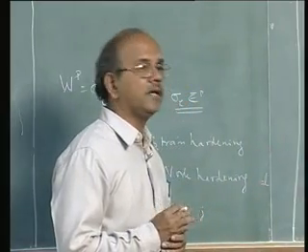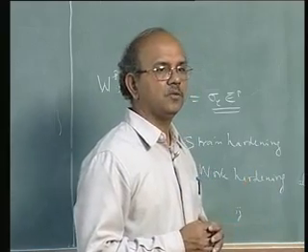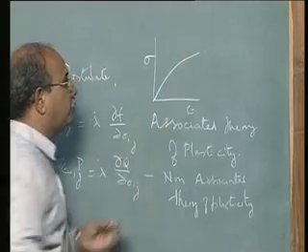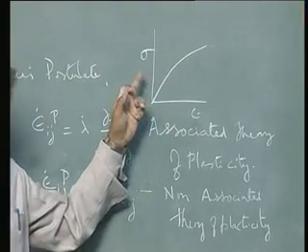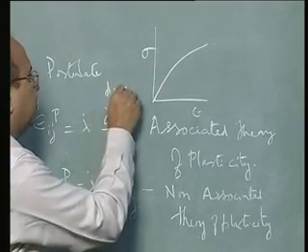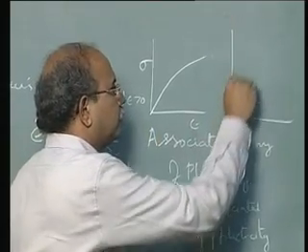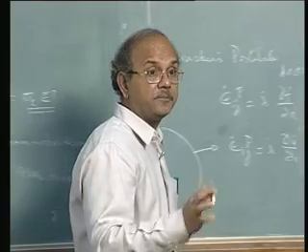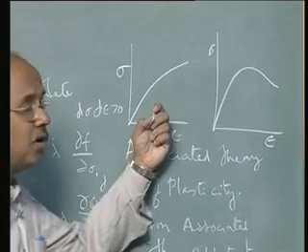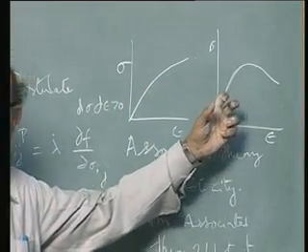Because of this postulate, we find that for stable materials, where we have stress strain curves, note that what we are talking about is the true stress true strain curve, when it increases, when d sigma d epsilon is greater than 0, as against materials where a curve can drop like that, sigma epsilon curves which are softening curves, these materials are called stable materials, or Drucker material. These materials are not stable materials.